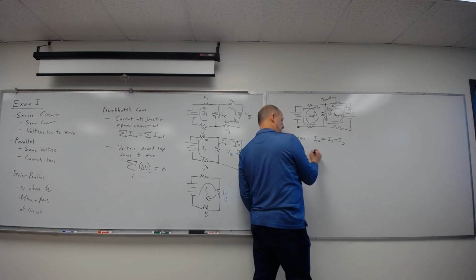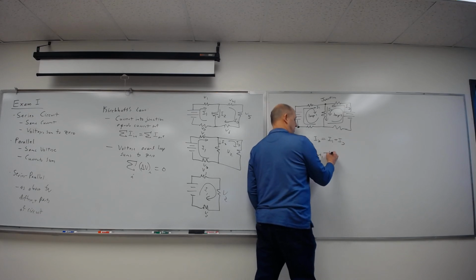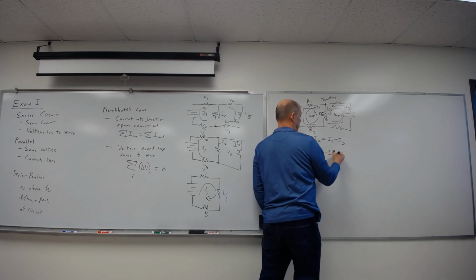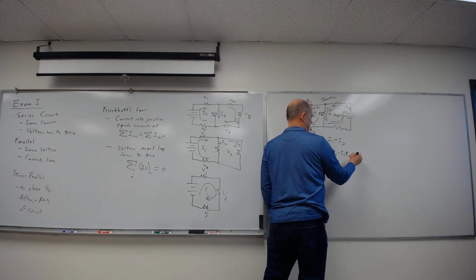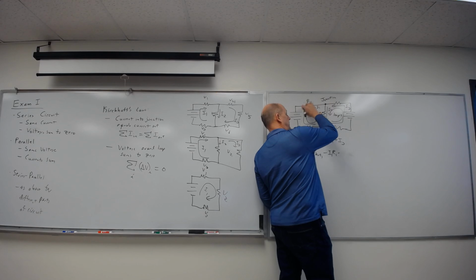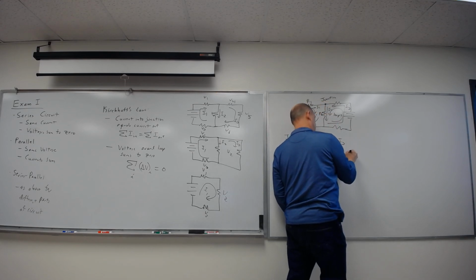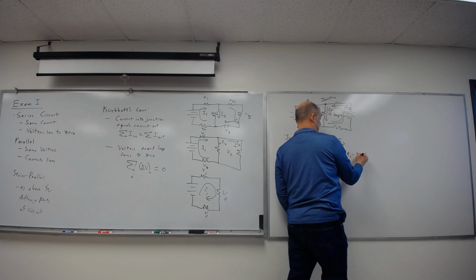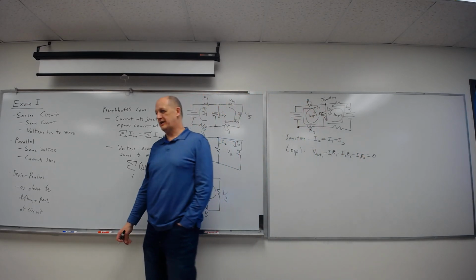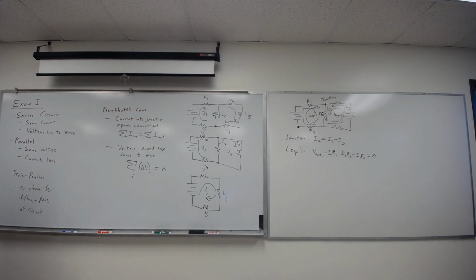And I'd put the battery voltage in, subtract current 1 through this resistor, called R1, R2, I don't know why I made that a 5, R3, so current, voltage drop, that all equals 0. So I go around that loop, the voltage I get brought in from the battery, subtract all those other ones.